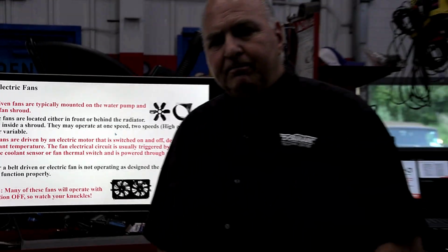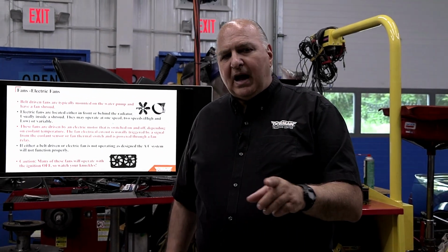Now the other thing here, here's a big complaint. I want you to write it down. I didn't put it in here because I want you to write some stuff, right? The handout will be available and all that. But customer complaint, when I do stop and go, my AC don't work well. I start driving down the highway, freeway, whatever you call it where you live, and guess what? It cools great. You know what may be the problem? The electric fan ain't coming on, okay? Usually on belt-driven, the fan will work, but if the belt is slipping, always make sure that the fan is working properly.